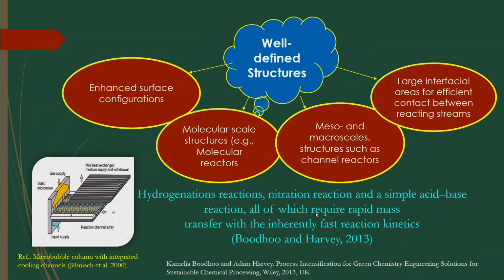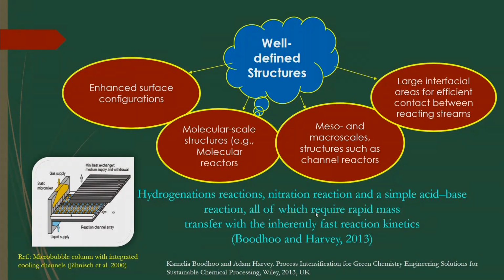So, enhanced surface configurations can be achieved by structured packing materials. Even sometimes the channel reactors, the microchannels, are configured in such a way as to get more gas liquid mass transfer there. Even for heat transfer operations, microchannel based heat exchangers are being developed nowadays. There are even some microbubble column reactors to get gas liquid reactions by generating microbubbles. So, in that case the configuration of the reactors is also important for process intensification.